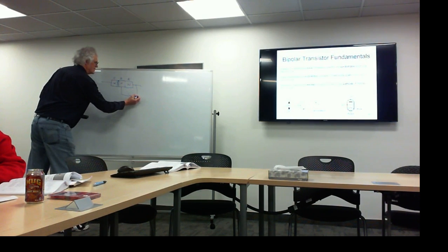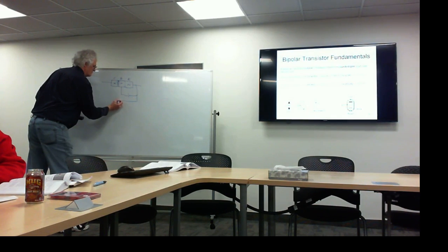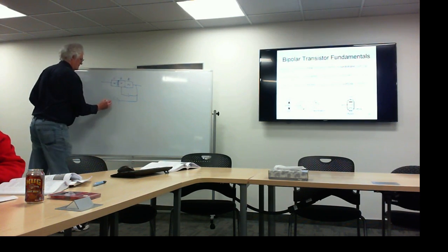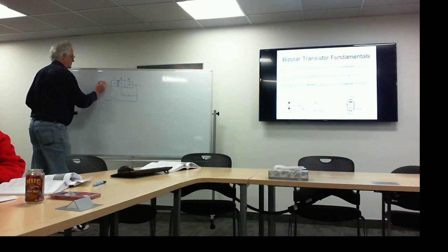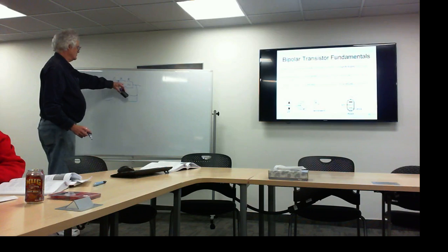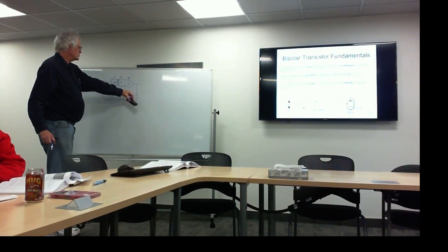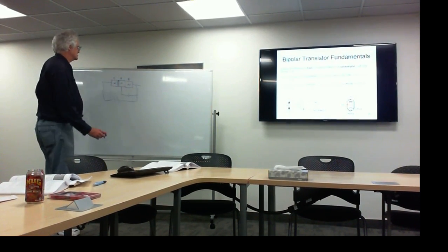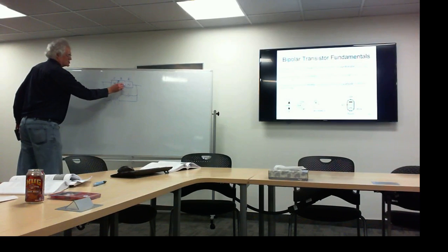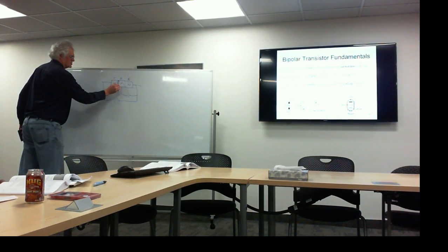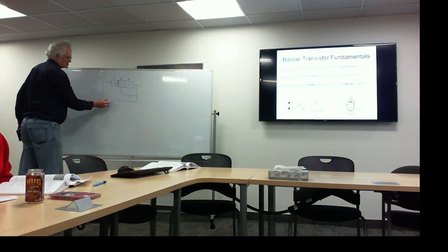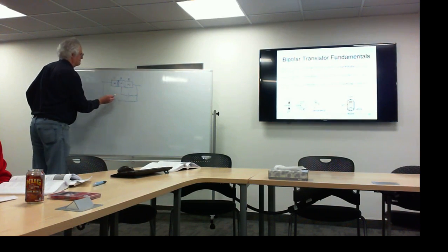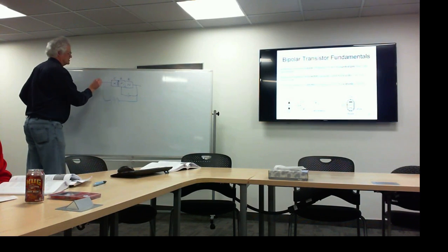So we've got conduction here. Now if we put a bigger amount of forward bias across the transistor, we've already got current flowing here. These electrons are already moving, so they'll just keep coming through and be attracted to that higher positive voltage. So now we have conduction through the transistor.